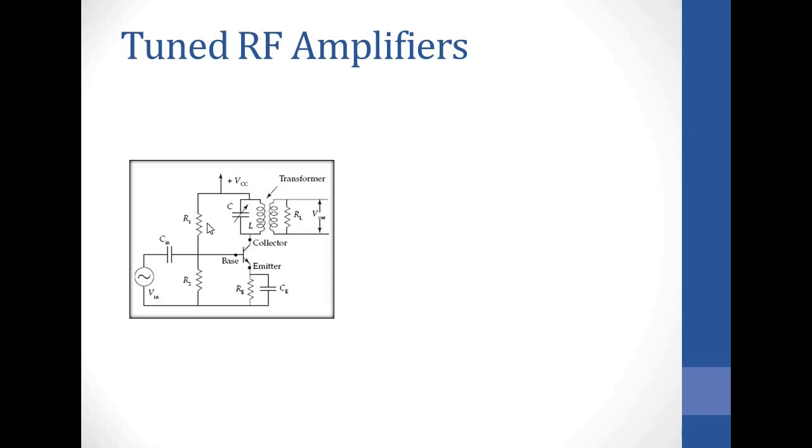It is also important for you to remember that the function of R1, R2, and RE is biasing this transistor. Biasing is basically powering the transistor so that it operates in the required region. And also it is important for you to remember that there are 3 regions of a transistor. We've got the cutoff, the active, and the saturation region.